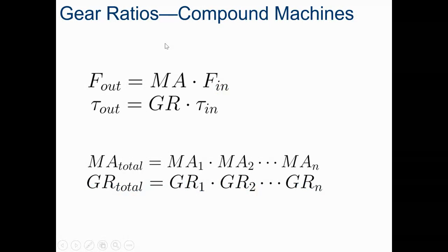All right, so one thing we want to do is compare this back to what we did with mechanical advantage and simple machines. When we did the simple machines, we talked about actual mechanical advantage being resistance force over effort force, FR over FE. If we take that formula and solve it for output force, or resistance force, what we find is that all we really need to do is take the mechanical advantage times our input. That is going to tell us our output force.